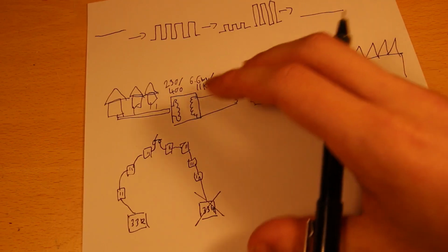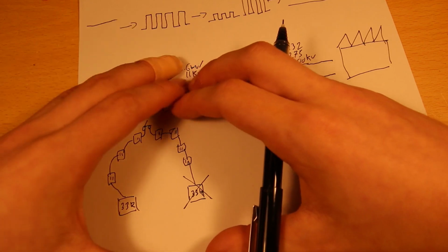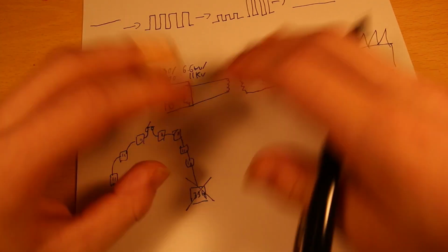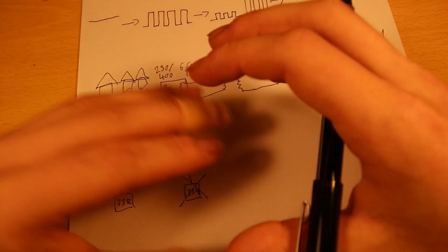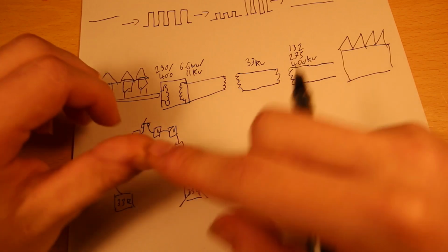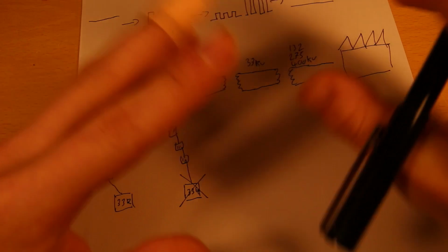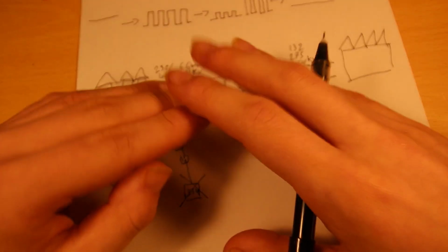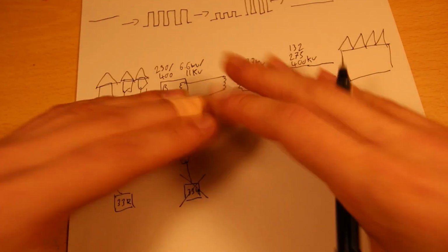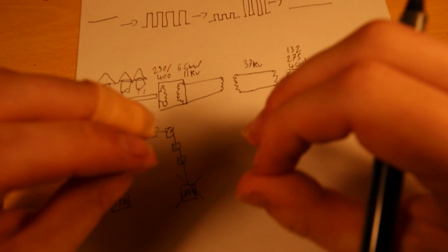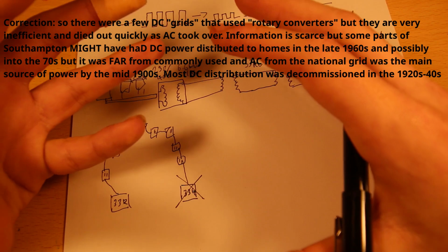The way it used to work back in like the early 1900s is you'd have one big power station and it would directly feed a voltage to a few customers in the immediate vicinity. So they used all sorts of voltages back then: 75 volt DC, 110 volt, 90 volt, 240 volt. There were countless different standards all competing. And they used low voltages distributed directly to the customers. That's fine, but you can only do that over a certain distance. I said the volt drop begins to become problematic.